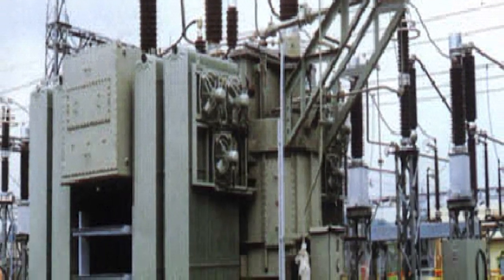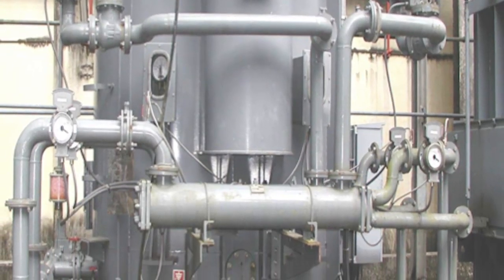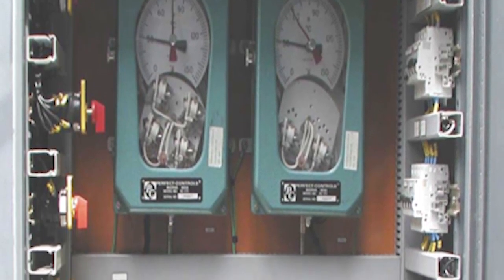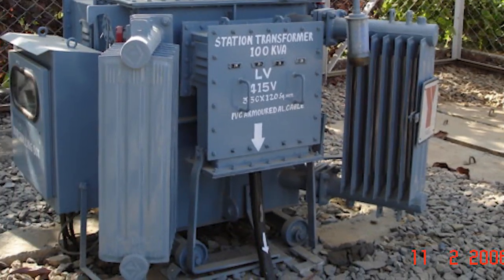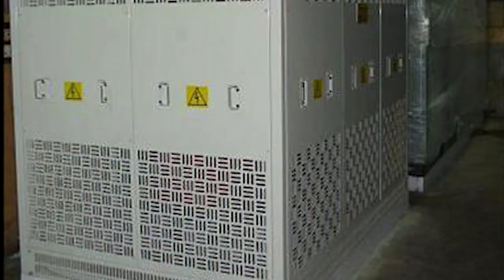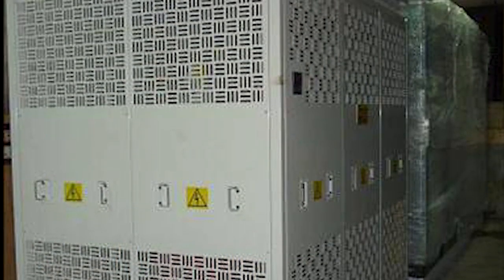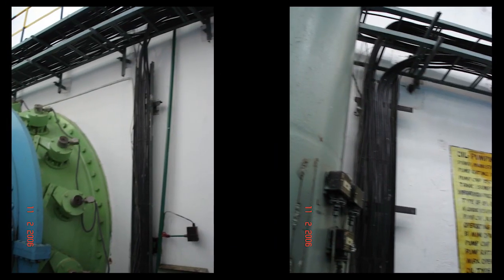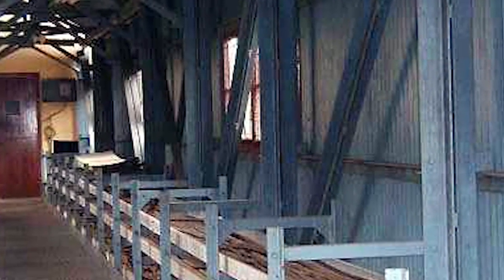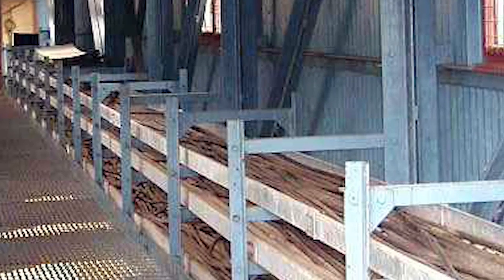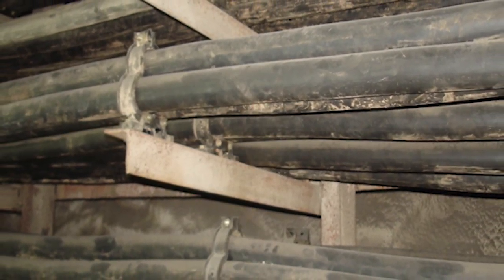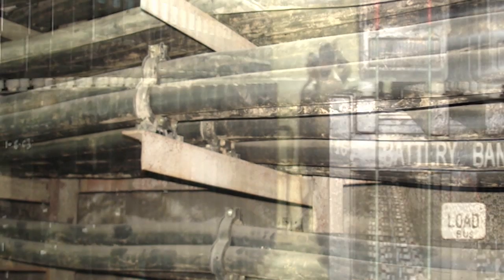Auxiliary transformers reduce the voltage level from the generated voltage level to 415 VAC. Similarly, there are station service transformer and excitation transformer. Power and control cable. They are used to connect all LT switchgear with the end-use system and to connect all electrical and mechanical auxiliaries in the power plant.